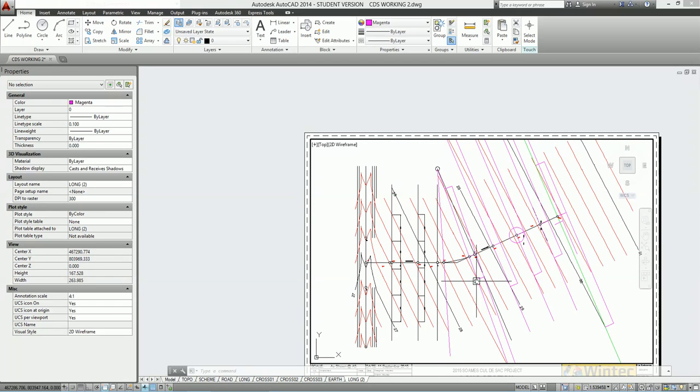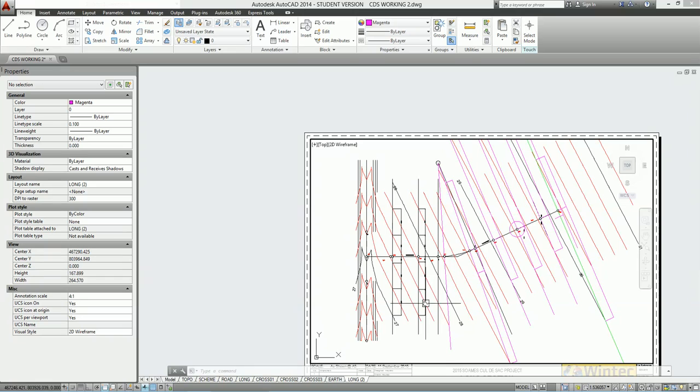When we get to cross-section 60, that is on the horizontal curve, so the cross-section runs on a line from a point on the curve through the centre of curvature, because remember that a radius is always perpendicular to the tangent. So the radius would always be perpendicular to the tangent at the point. So for cross-section 60 and 80, which are both on the horizontal curve, the cross-section line goes back to the centre of curvature.